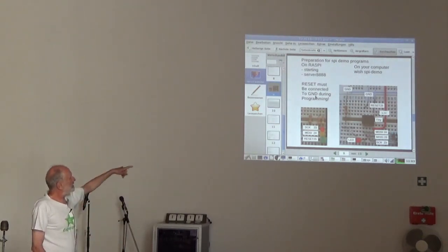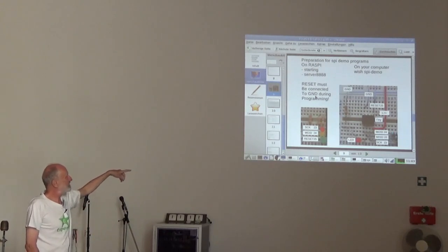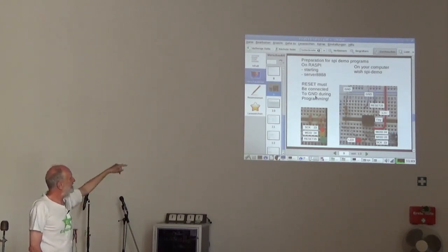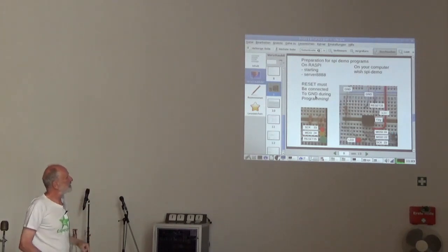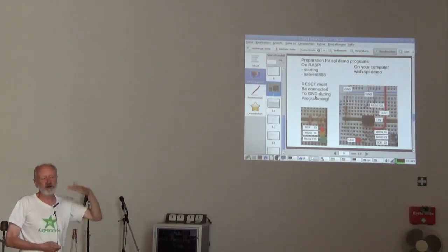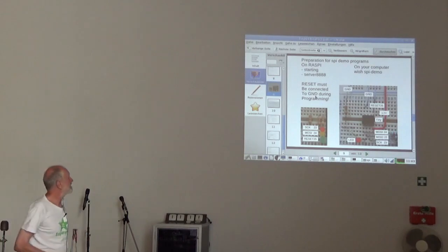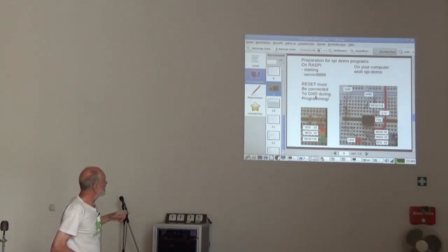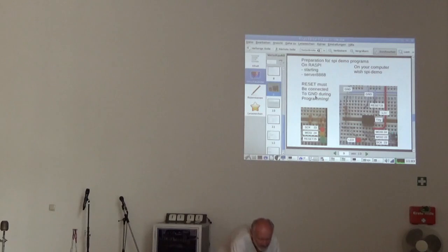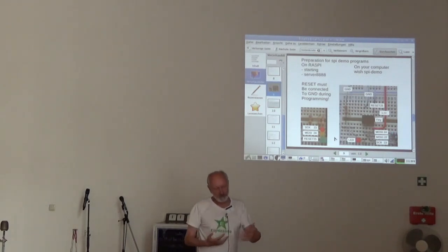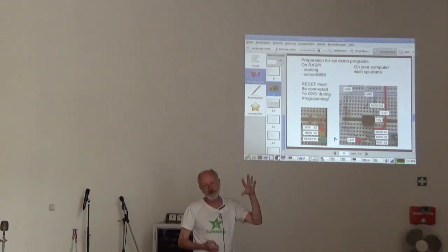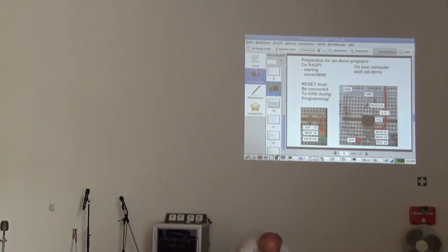This is a serial clock, master out, servant in, and there's the reset pin that must be normally high when the chip is running a program, and it must be low when you program a chip. And this can be seen now also in this demonstration mode. And finally, when the chip is programmed, then you will see a blinking diode.